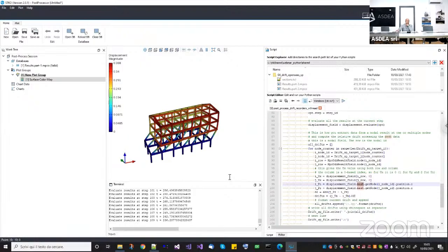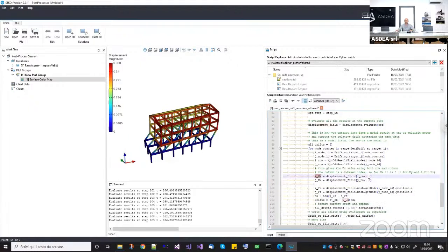Does it use the initial position or current position? Exactly as this question. It uses the initial position, okay? So the exact position that you put in OpenSees. If you want to get the current position, so the deformed configuration, for example, if you're doing large displacement analysis, you can simply get the total displacement, like this, for example. Here I'm getting just one row, just one scalar, because I asked for row and column.